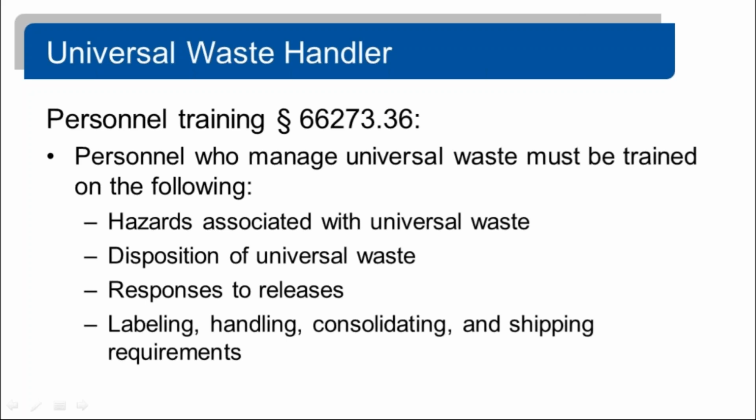So if they are handling the waste, if they're generating it and they're putting it in containers, and that's their responsibility, make sure that they are aware of the hazards associated with that activity, what to do if it spills, who to notify, where's the spill equipment, what types of hazards, and the types of PPE they need to protect themselves from. So that can be a brief, 15, 20-minute training on the specific types of waste they're generating.